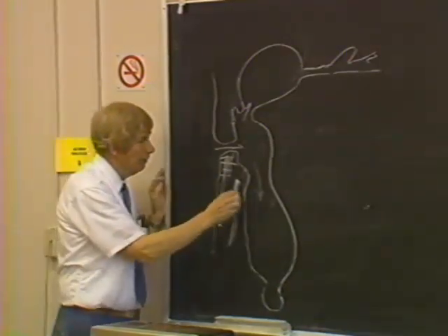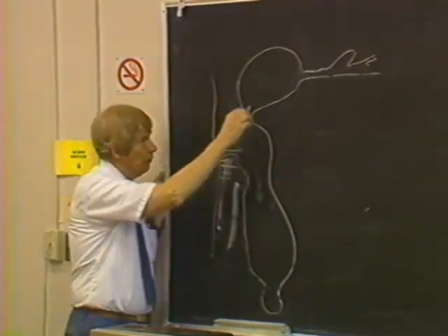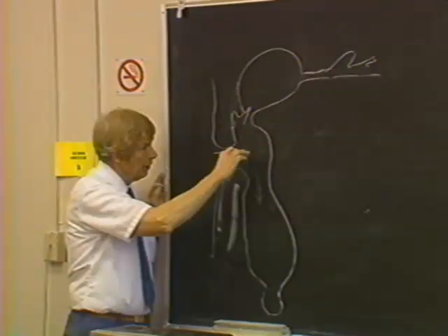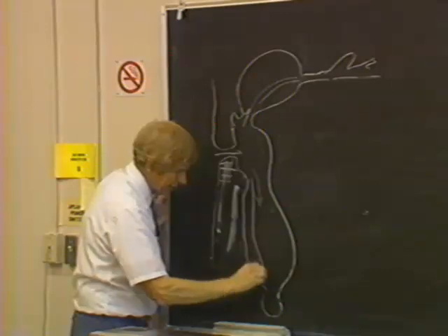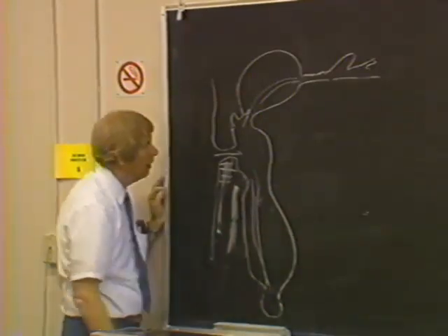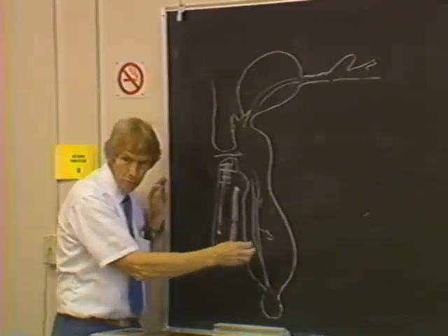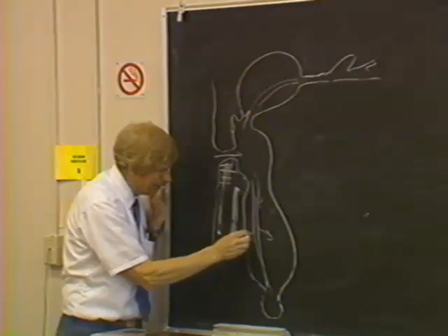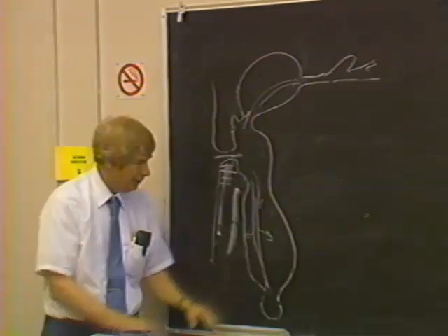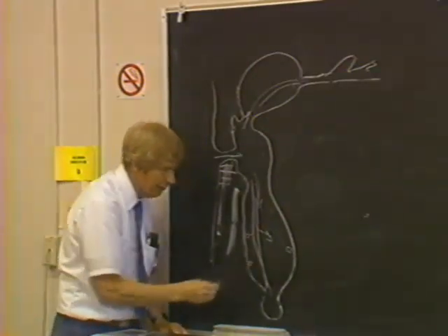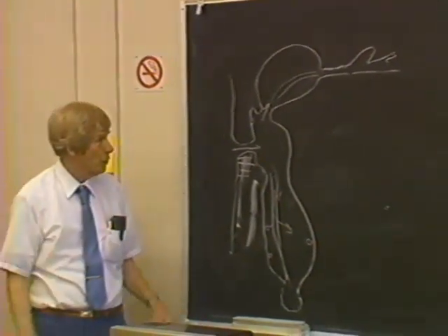And not only that, I didn't draw the channels in, but the flow from the channels, there's a channel going across here and a channel going down here. There's flow out of the channels and back into the channels during the reverse of the tide, which also causes some delay in tide stations. So if you have a tide station here and a tide station here, you'll find that they have peaks, high tides at different times, and low tides at different times.